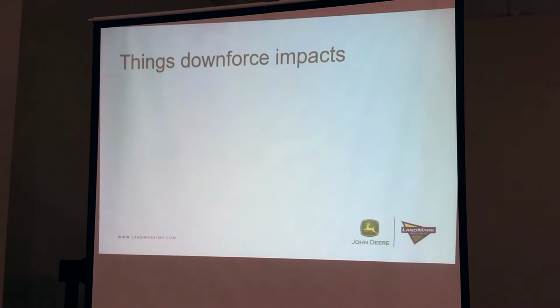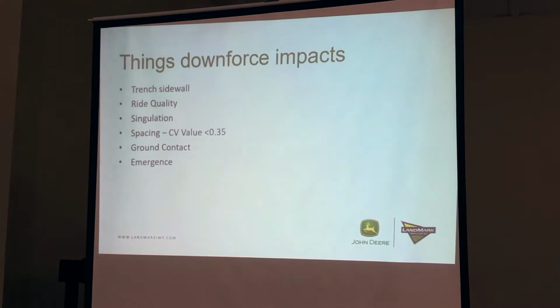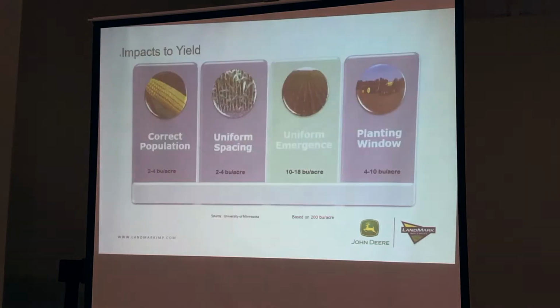Things that downforce impacts: it's going to affect the trench sidewall, ride quality, seed singulation, your seed spacing or your CV value in your display, ground contact, emergence, and most importantly, it's going to affect your yield, 5 to 9%. Impacts to yield because of your downforce.